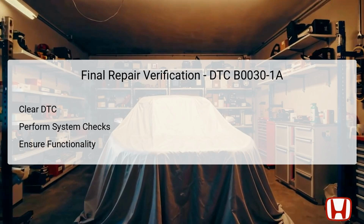Begin by clearing the DTC B0030-1A from the vehicle's onboard computer system. This step is vital because it resets the SRS system and allows you to test whether the DTC returns. Once cleared, perform comprehensive system checks to ensure all airbag components are functioning properly.